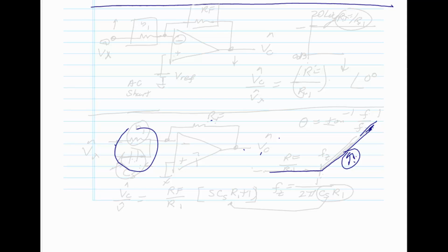I find the active circuits are actually much easier, because you're going to have an AC virtual ground, and you're going to have just the impedance transfer from the output to the input. It's output over input. So let's look at op-amp circuits where you have R1 and you have the negative terminal feedback, and you have RF, and you have a simple feedback where you may have a reference here, but AC ground.